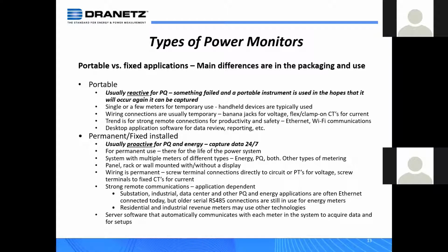From a power quality perspective, you can see power quality issues in your system that may not have affected you yet, but you could have a looming failure as a result of that. Sags, swells, transients, harmonics, or other issues that maybe have not caused failures today, but you need to look into to improve your uptime and prevent those failures for tomorrow.